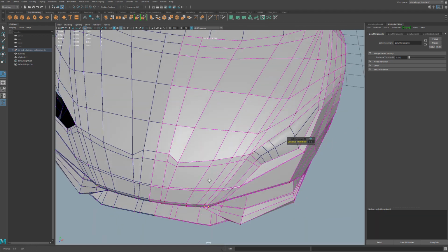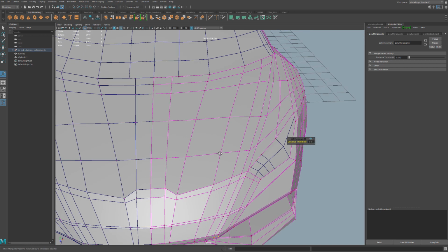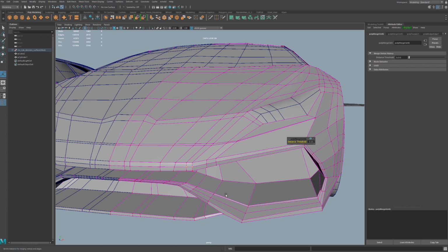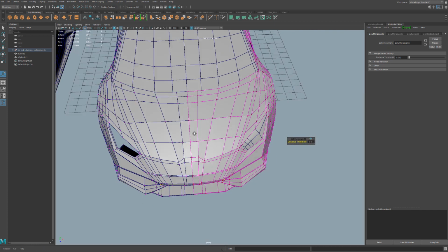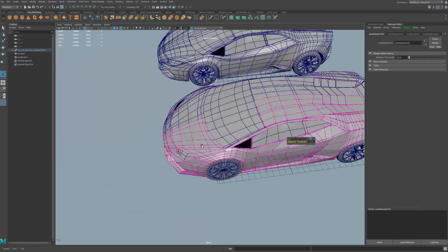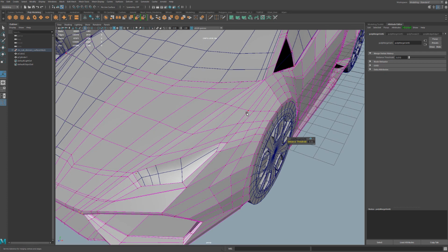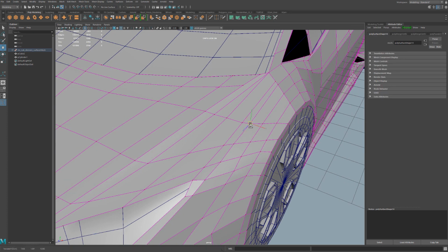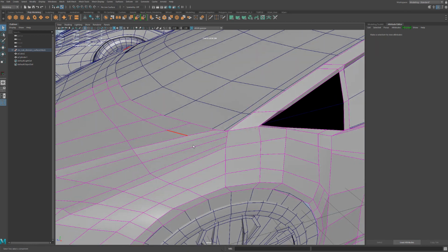All right, this is looking quite a bit cleaner. Let's go ahead and introduce those panel lines. At this point I would clean up the bottom of this, but I think I've done enough. Once I'm happy with the front, back, and everything at this resolution, with my topology flowing like it should, I would start introducing those panel lines again. We could drop another loop and connect it to this or merge it, and then slide all the other ones. So do something like this.